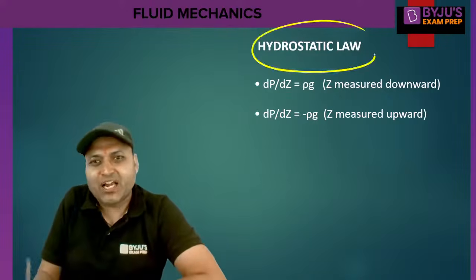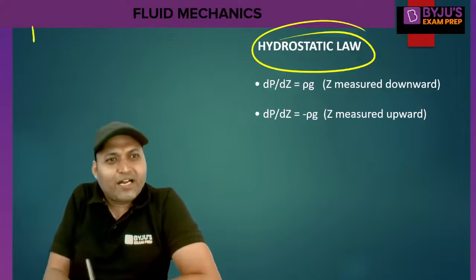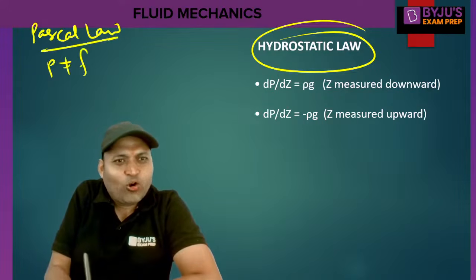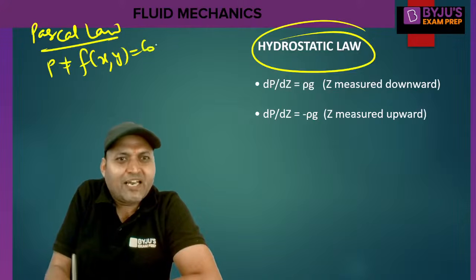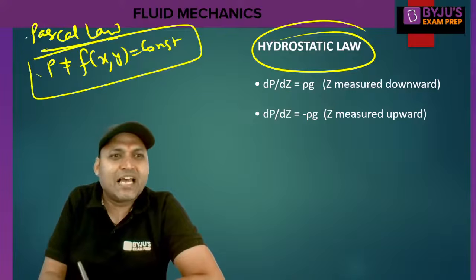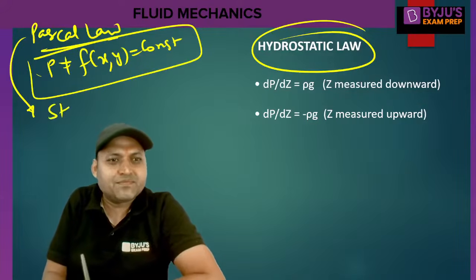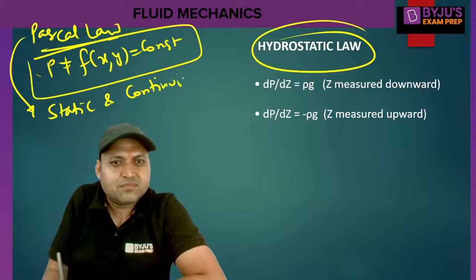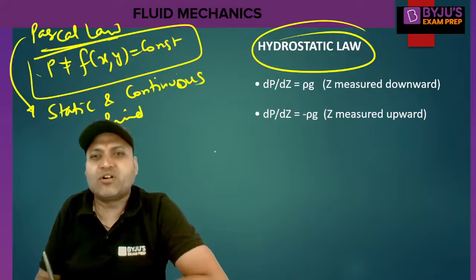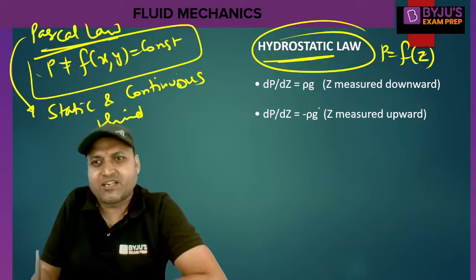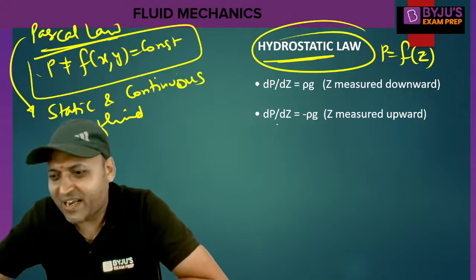Then the hydrostatic law. According to Pascal law, pressure is not a function of x and y. Pressure in a horizontal plane remains constant. In a static and continuous fluid, pressure in a horizontal plane remains constant. According to hydrostatic law, pressure varies in the vertical direction. The variation of pressure in vertical direction.